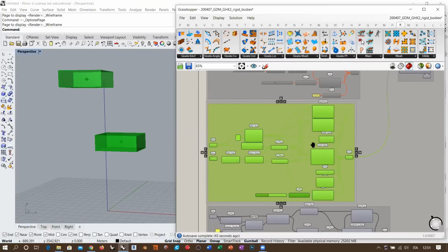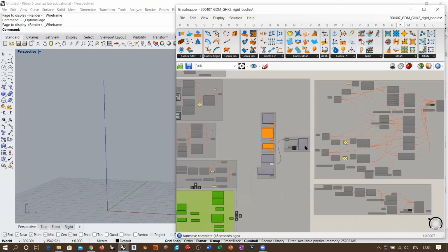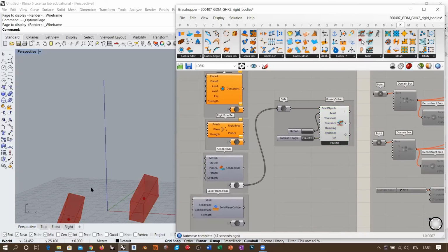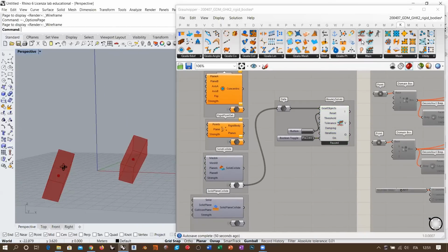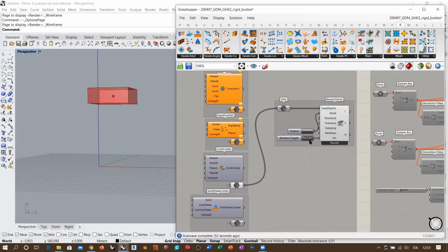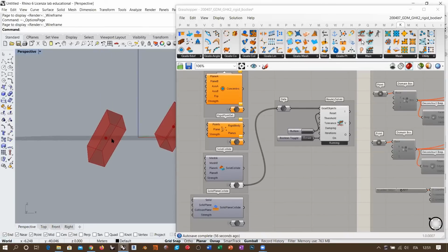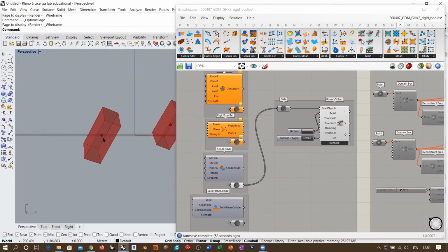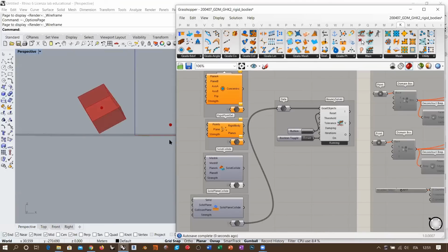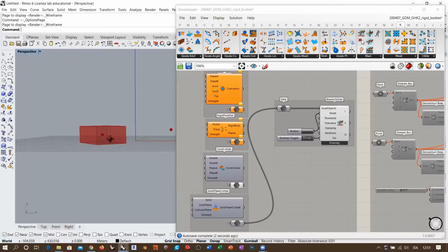That's why when we run this simulation, we see that the object falls down, especially the first one, which is subject to gravity, until it touches the floor, but its centroid is aligned with the floor, not the body. While if we work with a solid plane collision, it's the rigid body that interacts with the floor in this case. So it's not the centroid, it's the whole body.